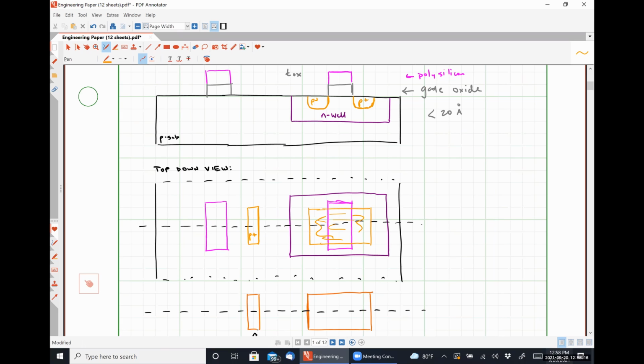So the invention of this technique occurred in, I want to say, the late 70s, early 80s. Before this point, gates weren't made from polysilicon at all. They were made from aluminum, which is why they're called MOSFETs. It's metal oxide semiconductor. Well, now it's really semiconductor oxide semiconductor. We just dope that first semiconductor region so much that it behaves as if it were metal, or pretty close, right? Sheet resistance of this highly doped poly is on the order of 20 to 25 ohms per square.